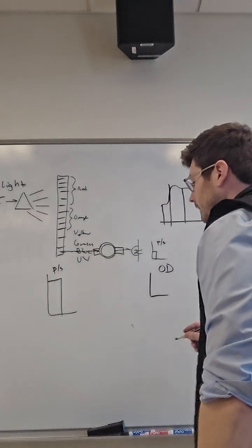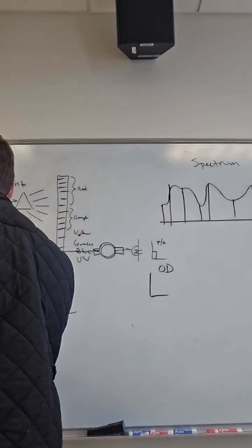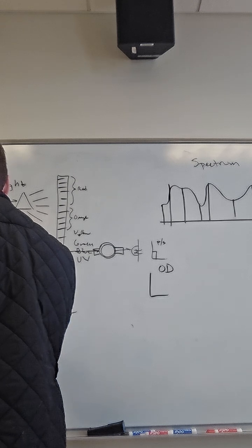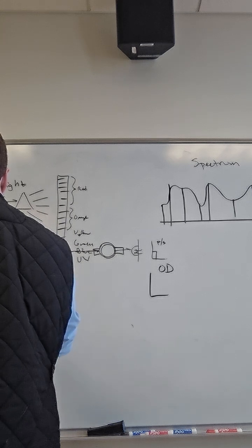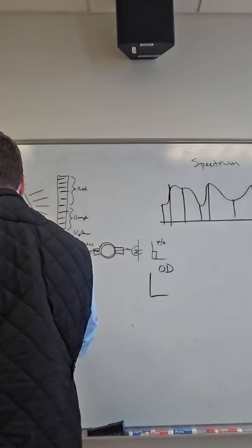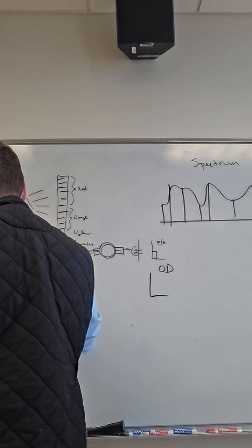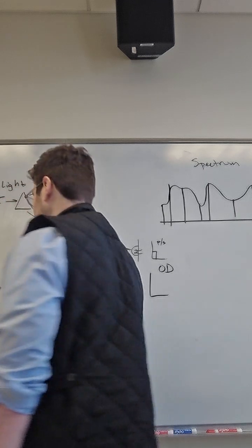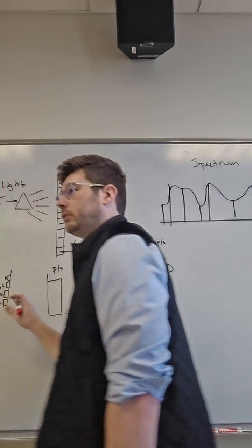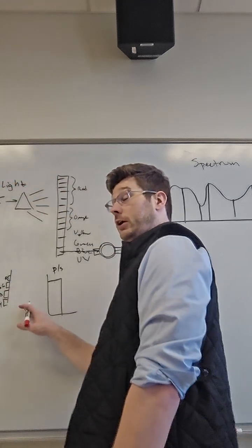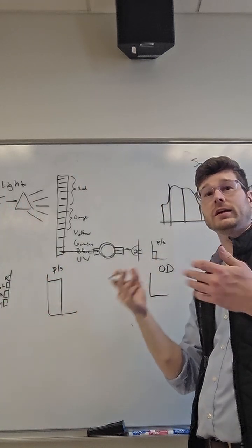Okay, the other way of doing it is similar, where we have a white light emitter again, but rather than filtering that light, we don't have a prism this time, we just pass it straight through our sample, but then our photodetector is the thing that is sensitive to different wavelengths, where we would have a red detector and a green detector and a blue detector and a yellow detector and so on. That is another way of doing color detection. We're essentially just detecting changes in light intensity versus light.